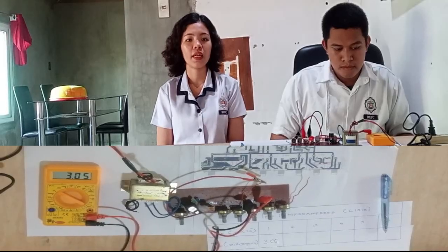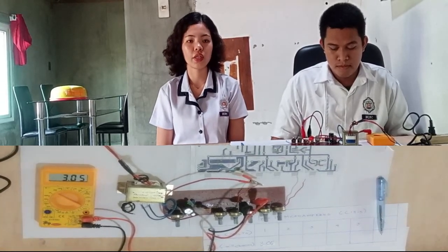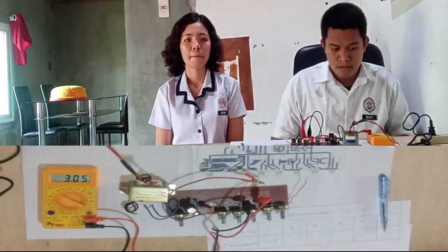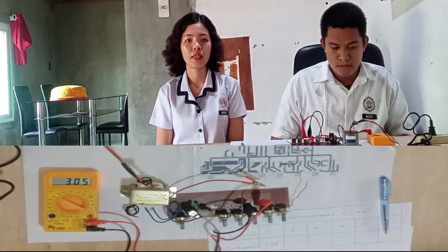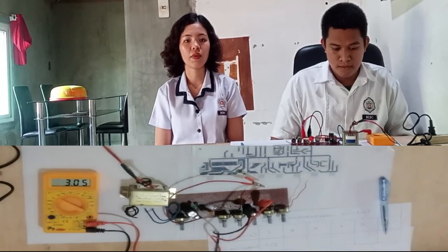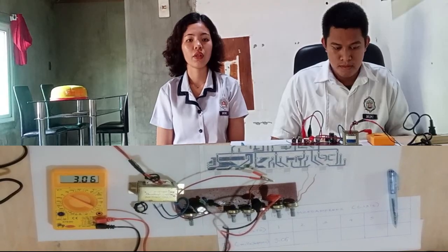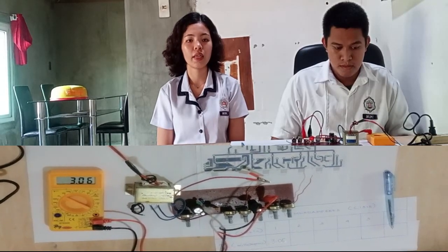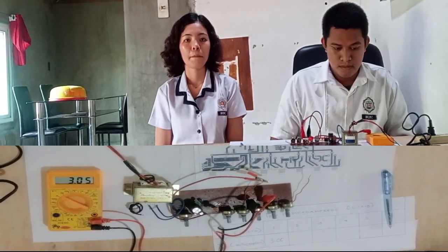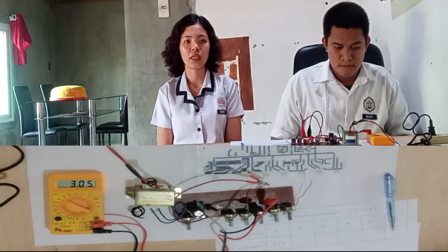Now, complete the table in Figure 2-4 by adjusting to the remaining values indicated and recording the corresponding values of collector current. To do this, simply repeat steps 5 and 6 for each of the remaining values in the table. When you complete the table in Figure 2-4, we have a permanent record of collector current values over a range of collector to emitter voltage values when base current is held constant at 10 microamperes.